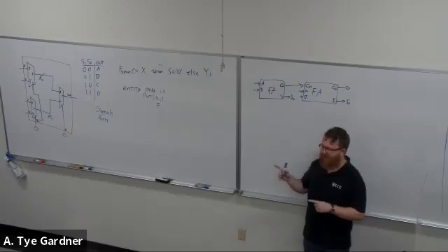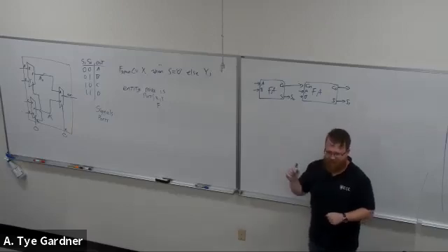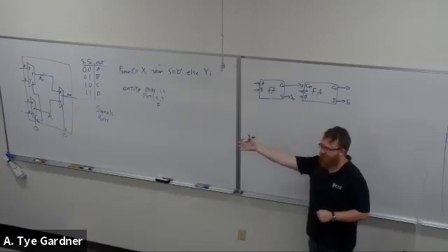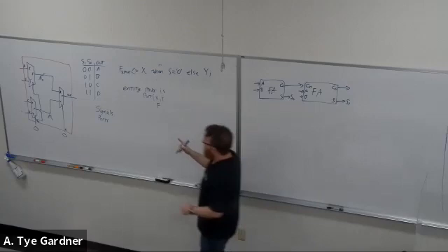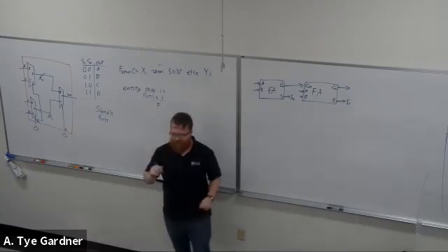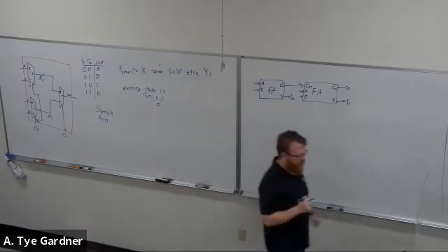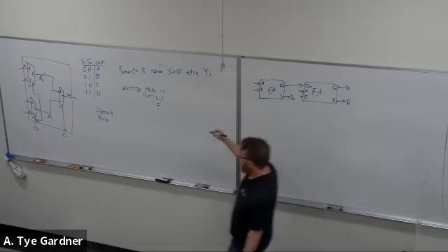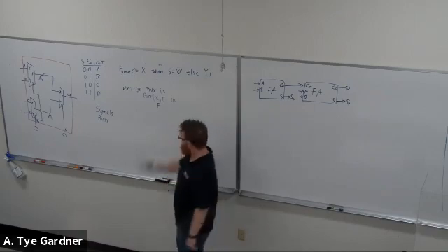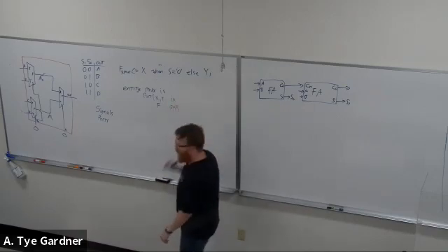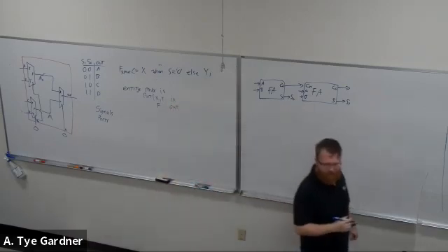Outputs don't like anything else to drive a signal into it, okay? It's outputting something, it doesn't want something shoved back down its throat, okay? So F is my output, but before I can do that, I need to tell it, well, those are ins. This is an out. Now it knows, okay?